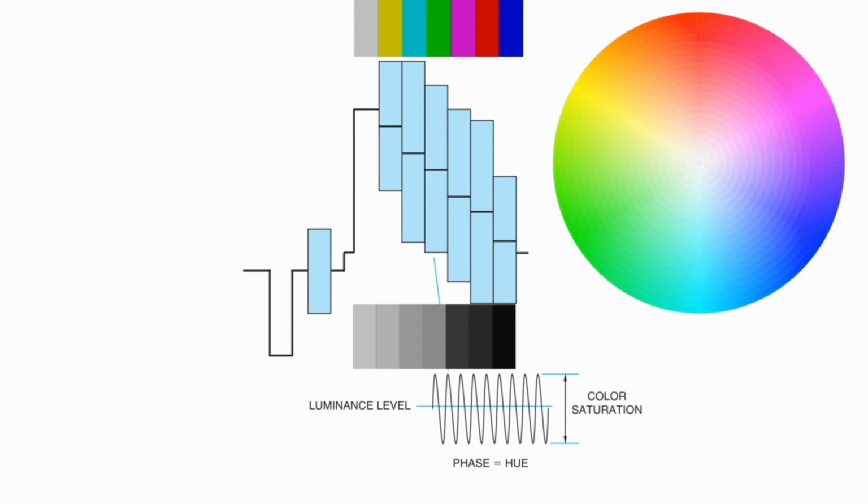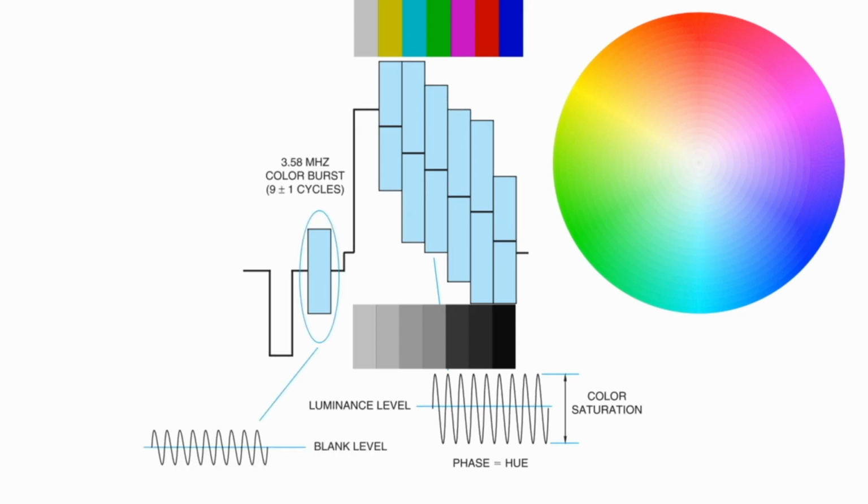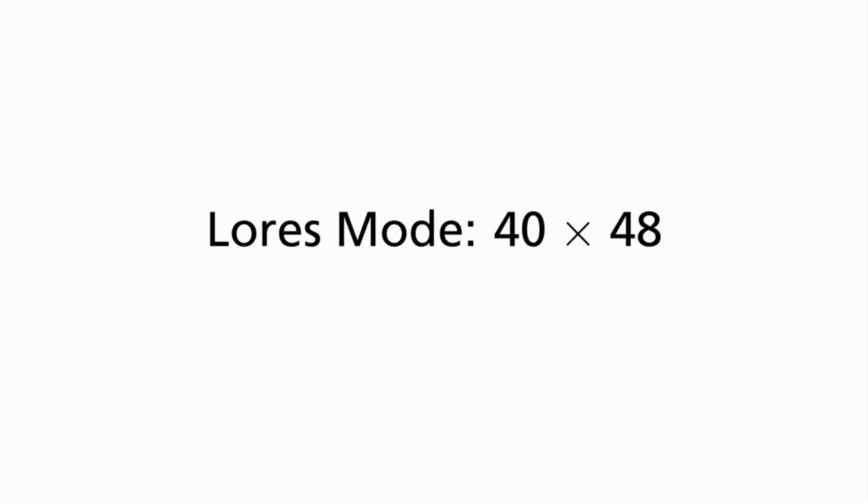As you might imagine, it's important to get the television to agree with the broadcaster about the phase of these oscillations. To do this, a color burst signal is sent at the beginning of each line of video, but off screen so you generally can't see it. Now you can understand Woz's color trick. The Apple II video circuitry runs at about 14.3 megahertz, which Woz chose to be exactly 4 times the color burst frequency. So if the Apple II outputs a digital waveform with period 4, the TV will interpret the waveform as color and display it as such.